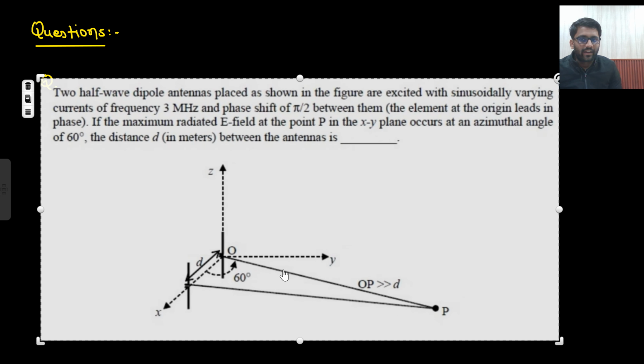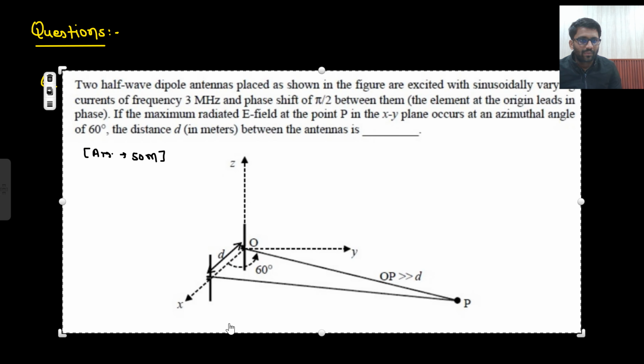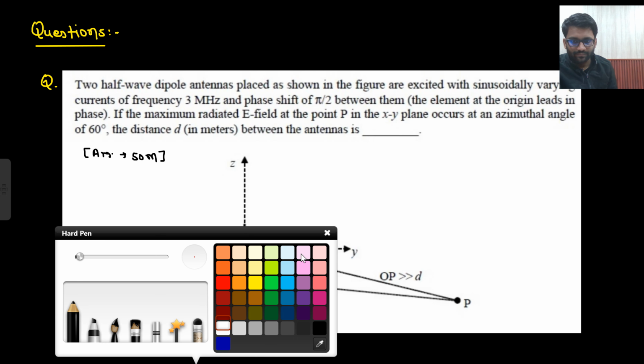It's a very random diagram. So I will tell you how to solve these kinds of problems. But believe me, you know every single point about it. So no formula mug up, nothing. Zero formula we are going to mug up in antenna array. We will just solve by the method. What is the method? No matter how many antennas are there, always assume a single element at the origin, having current I naught, having zero phase, and write down the electric field. That is the first job you have done. The second job is to write the array factor, and that method I have told you.